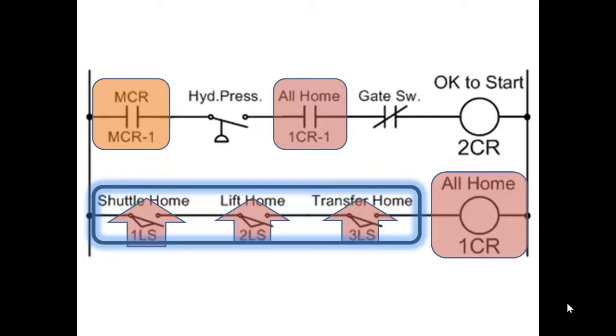And right now, the hydraulic pump is pumping up the pressure in the system because you don't want to start the machine until you're up to full hydraulic pressure. So at some point, that normally open switch is now going to close because that switch has an operator inside of the hydraulic system, and the pressure pushes it closed against spring tension. That spring tension is adjustable, very much like the regulator that we showed you in another lecture on basic electricity and magnetism. So the master control relay is reset, so it's safe to start.